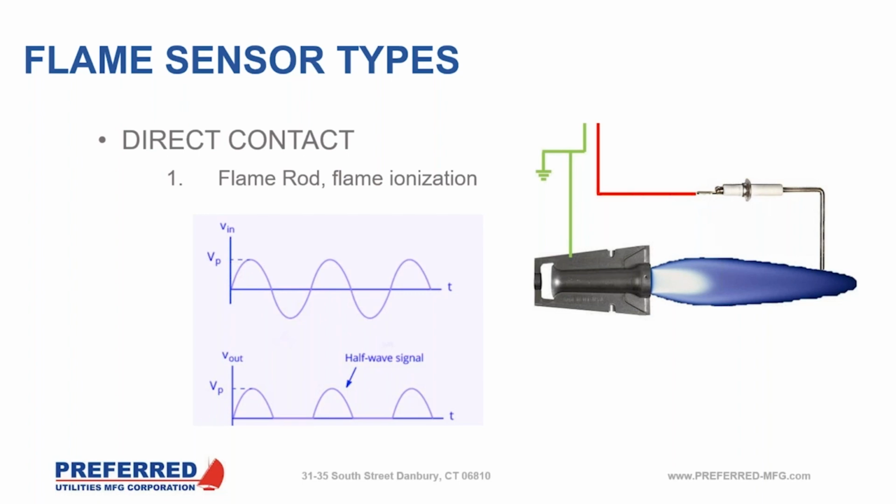So we start loading that and it'll start dropping back. This is why we call it flame rectification. So we can determine that, yes, we do have a flame signal at that point and it's not a short. So it has its uses. It can be really, really effective in a lot of applications.